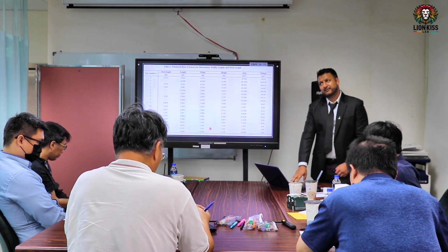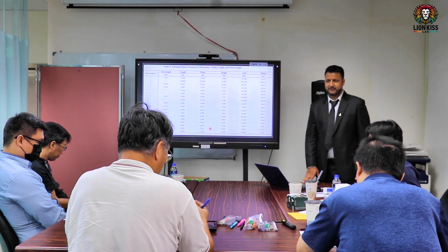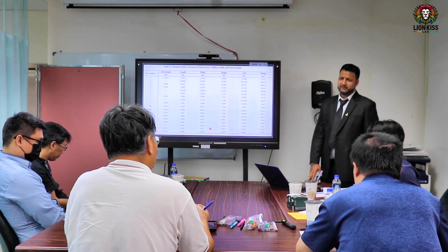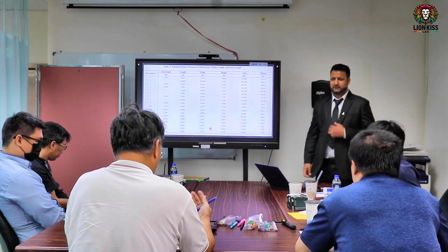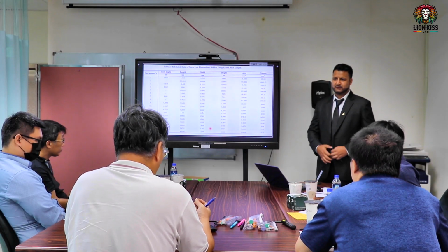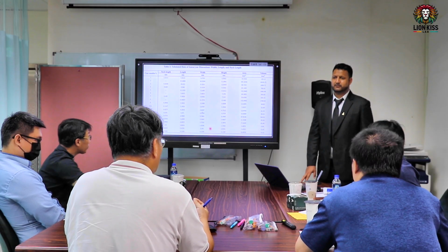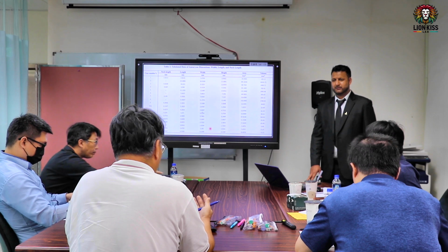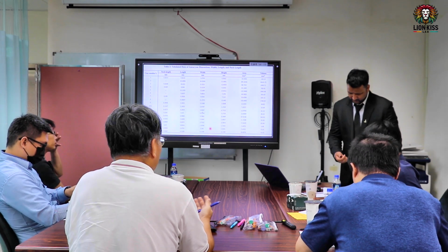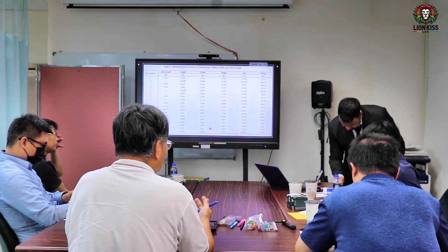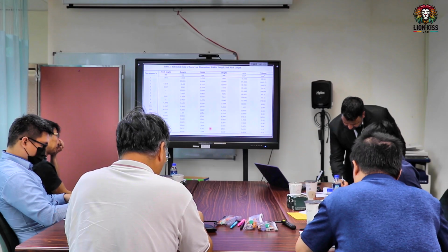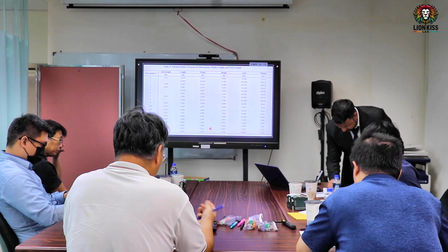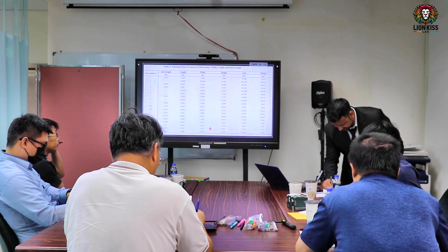Well, it makes sense in such a small blood vessel. Usually it's laminar, but sometimes the pressure is so high. So sometimes you need to quantify the Reynolds number in your CFD simulation. You can base it on probably the maximum velocities you find, and use that to justify that the laminar flow model is appropriate in your case. Okay. Sure.